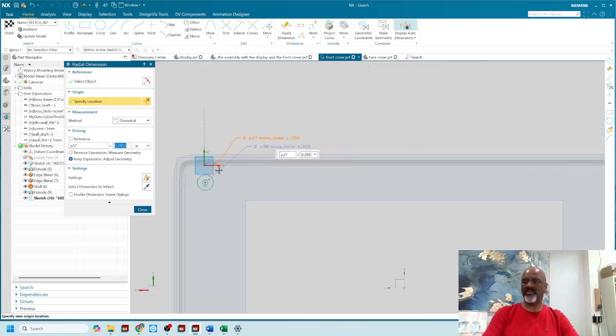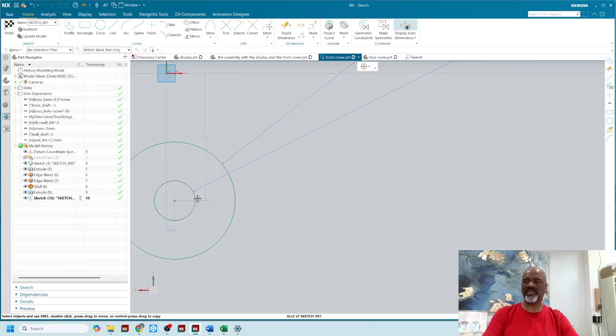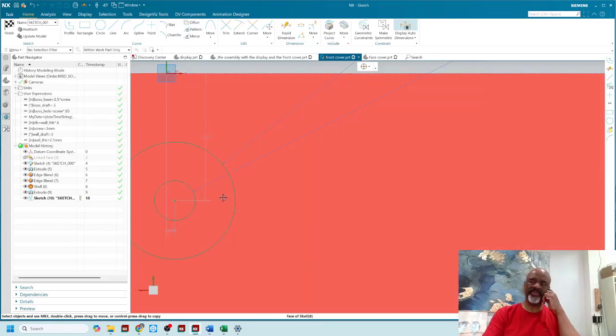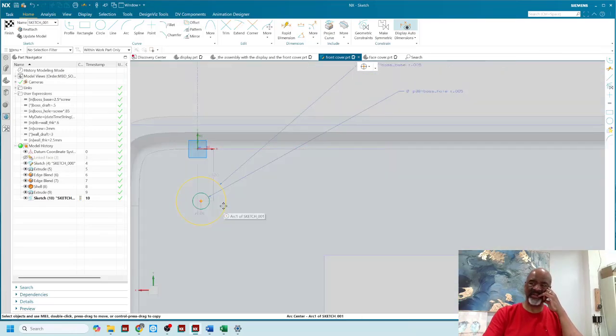And somehow I messed it up because what we have to do is make sure that the thickness of the rib, the wall of the rib, is only 65% of the nominal wall thickness. So what I'm going to do is I'm going to delete this. I don't know why this is so wrong. And I'm just going to do one more pause.